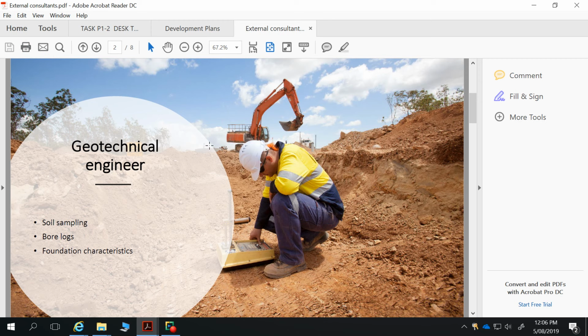And as I mentioned earlier today when we were out there, that's typically going to be on the back of a Land Cruiser size, full drive rig. You can get them into most places, and they'll get the soil samples done. But you're not constrained to that. Sometimes, as I said before, you can do a soil sample inside a building. It's just much more annoying to do so. You've got to carry the A-frame in there, take up floorboards, push your push tube in there with a two-stroke hammer, and then pull it all out and get your soil samples done that way. All these things can happen. It's just a little bit harder in some situations. And also for hilly sites where you've got limited access, it might have to be all manually done. But it can be done.